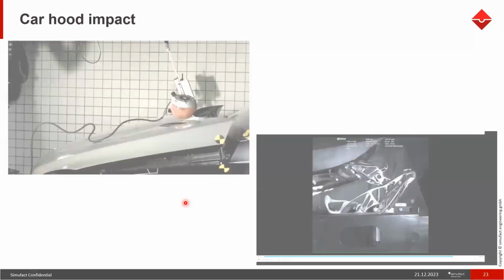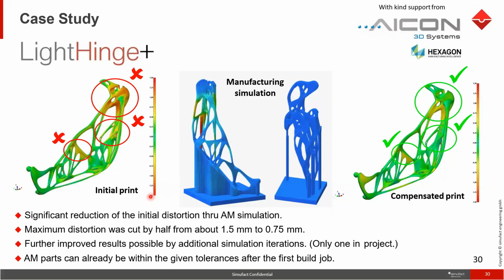Coming to this one, this is the part, and coming to the manufacturing of this part, how do we manufacture it? For example, when we manufacture these kinds of parts, we find issues with respect to distortion, because there are some thin areas and a substantial variation in the cross sections as well. So these kinds of parts are difficult to manufacture.